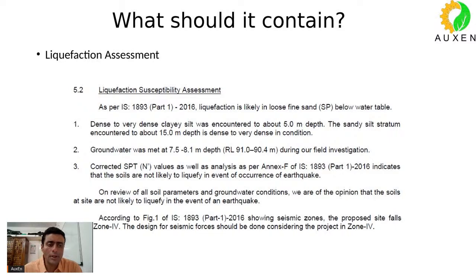They have given you the liquefaction assessment. When do we have the problem of liquefaction? As many of you know, in case of an earthquake, we may have to check whether or not your soil has a tendency to liquefy. If your soil liquefies, what will happen? It will lose its shear carrying capacity and your structures might fail. So liquefaction only happens under the effect of lateral or seismic shaking.